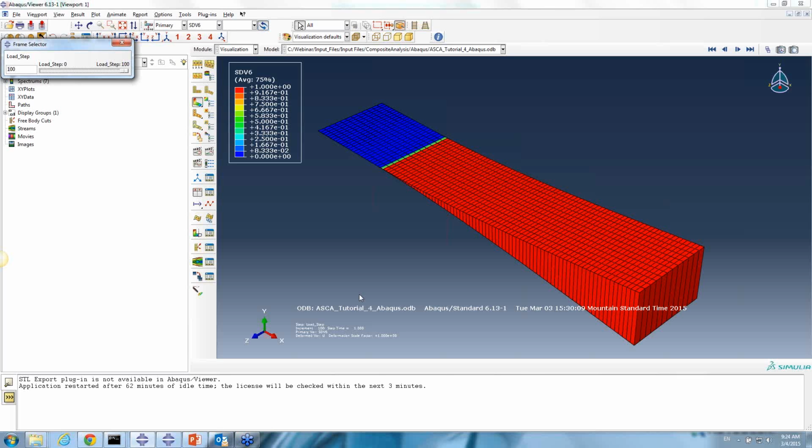But if you have a sample that you're using and you're not sure if cohesive damage is going to be occurring, you probably don't want to introduce this cohesive technology in there. It's just not effective use of your time. So try to avoid it unless you're trying to model that in your simulation.